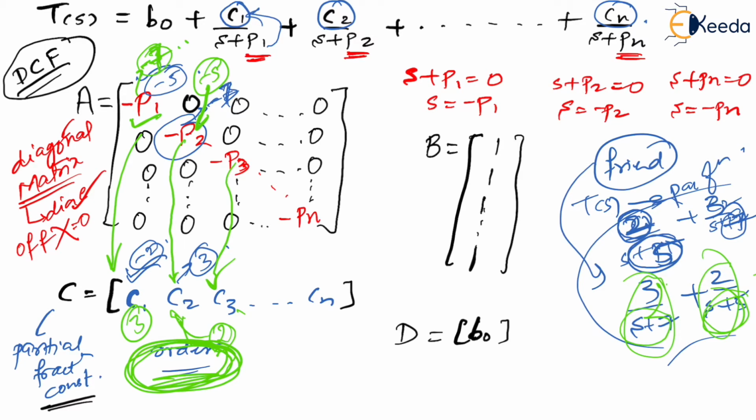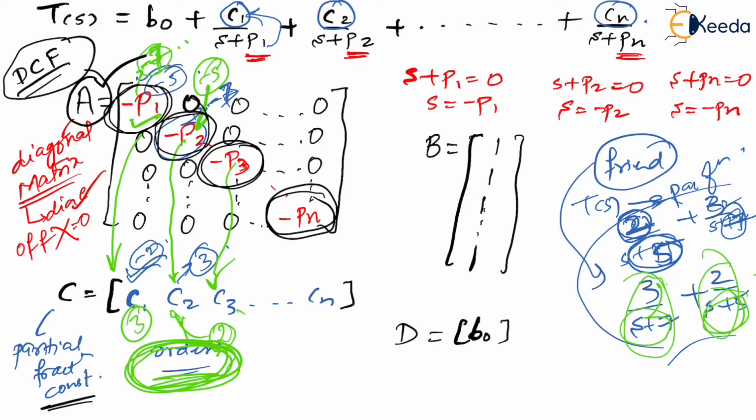So it is important because the moment we bring the transfer function or the system into the diagonal canonical form, we can see whether the system is stable or unstable very easily just by observing this matrix A. Getting my point? Just by observing this matrix A, you will understand why. How? Because you can see these poles directly. So just by looking at this matrix A, you can comment on the stability, whether it is stable or unstable. Right?